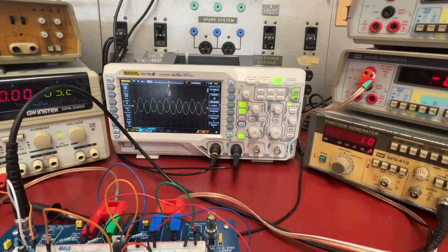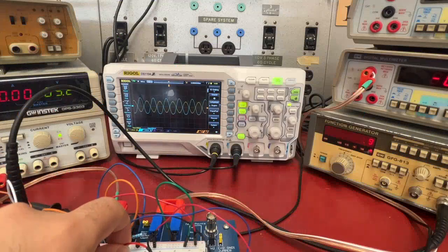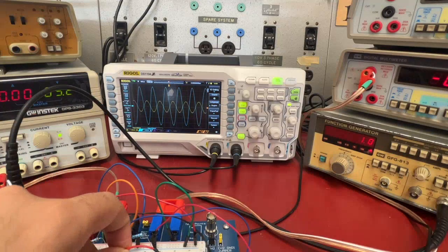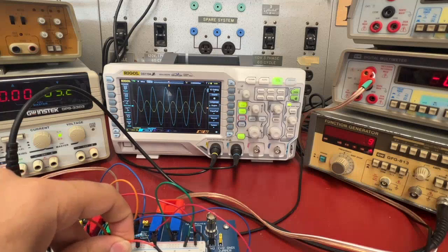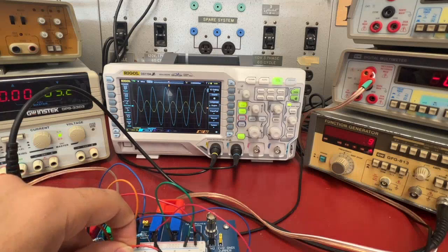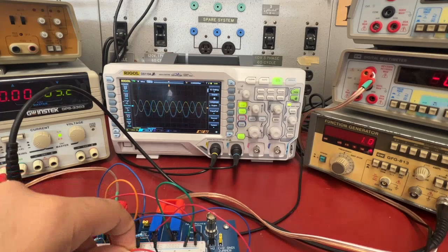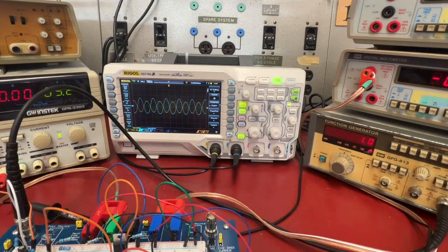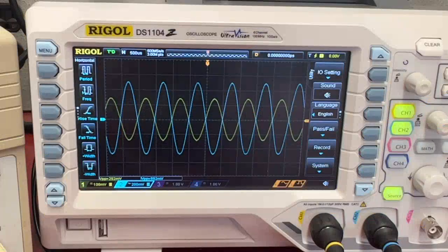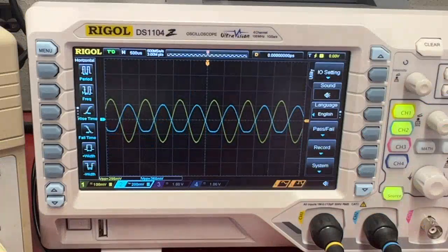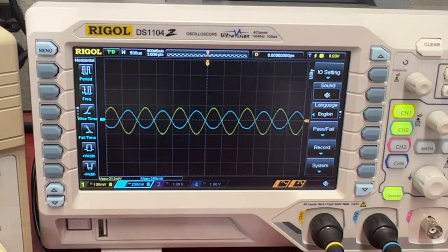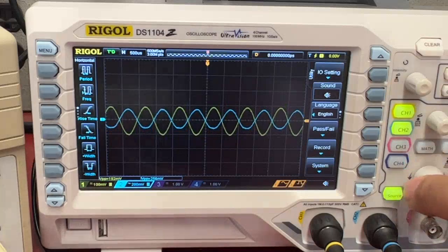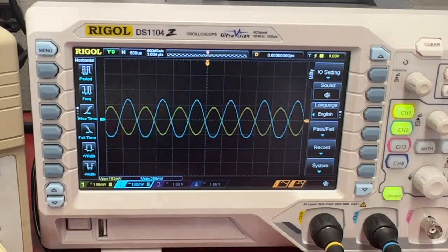The gain reduction is mainly because of the low impedance associated with the speaker. So as I disconnect the speaker from the circuit, the amplitude increases. In this case, with the speaker disconnected, we only have a 1K resistor as a load of the follower amplifier. But as soon as I connect the speaker in parallel to the 1 kilo ohm resistor, the amplitude reduces significantly. Also, you can see how the speaker responds to different frequencies of the source signal.